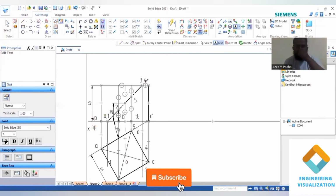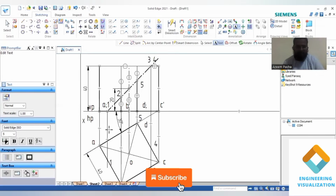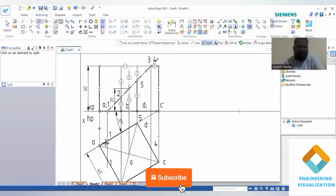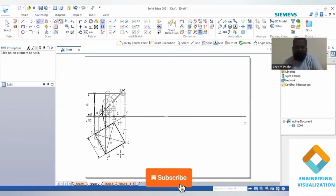So 5 we are getting exactly on the vertical edge D here. Now we have to draw the development of this. And this is exactly 1. Now in this top view I am going to measure this length. In order to measure it, before that I am going to split it to the exact length, so that we are able to measure it, and the same length we can cut in the development part.